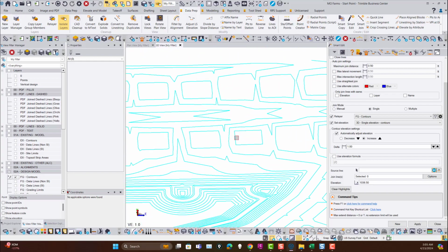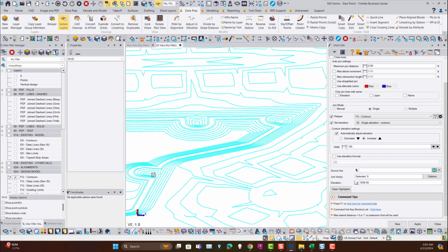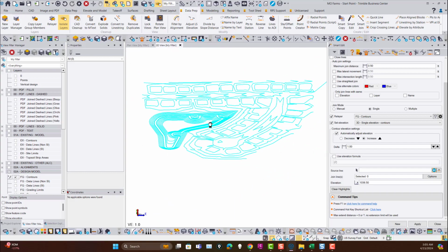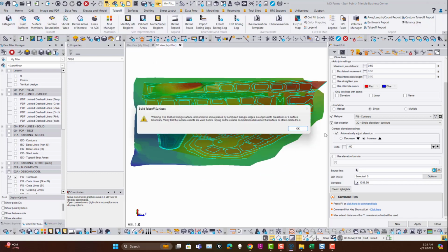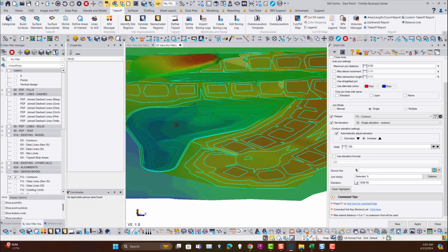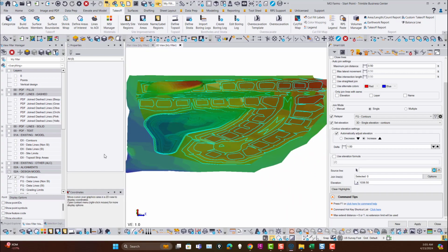Like this. And you can see these contours are all forming nice pond contours here. And if you're now ready, you could now run build takeoff surfaces, for example, in takeoff, build surfaces, and that will build me my finish grade and my existing ground models for my contours. So very quickly there, I turned my data from 2D imported PDFs into 3D elevated contour lines.